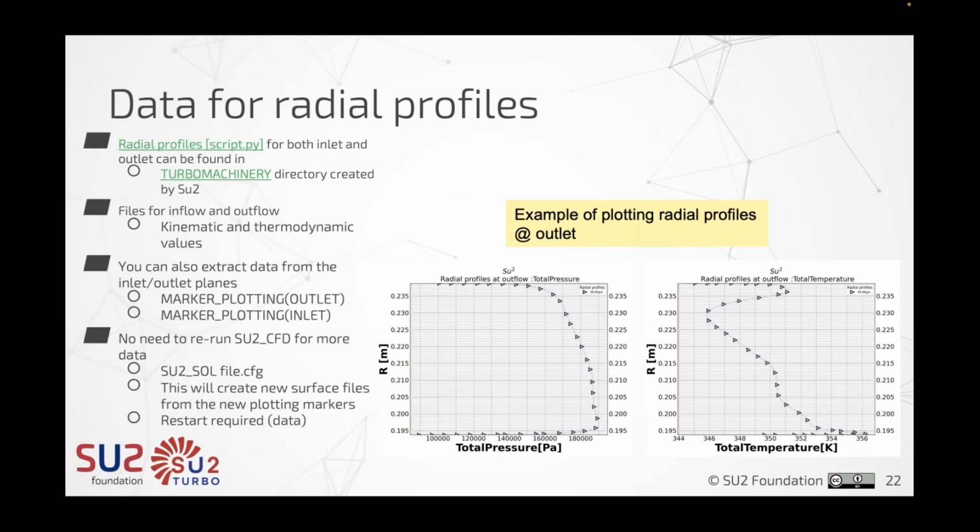But now there are unstructured meshes because you want to add more geometrical effects within the blade configuration. So unstructured meshes are being used more, but near the boundary layers, it's mostly structured. Yeah. But in 2D cases,